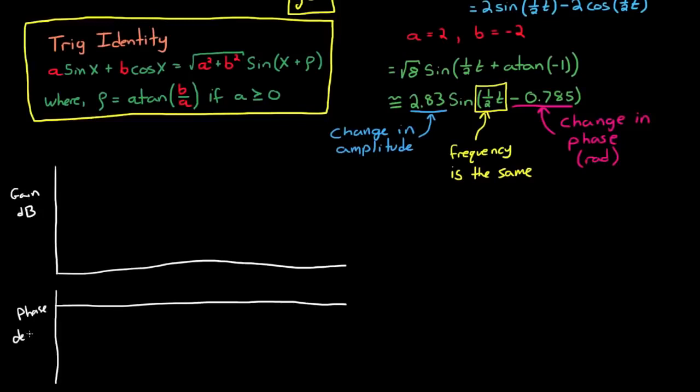Well, one way to do that is with the Bode plot. The Bode plot allows frequency response information to be displayed graphically on 2 separate plots, one for gain and one for phase, both of which are plotted against frequency on a logarithmic horizontal axis.